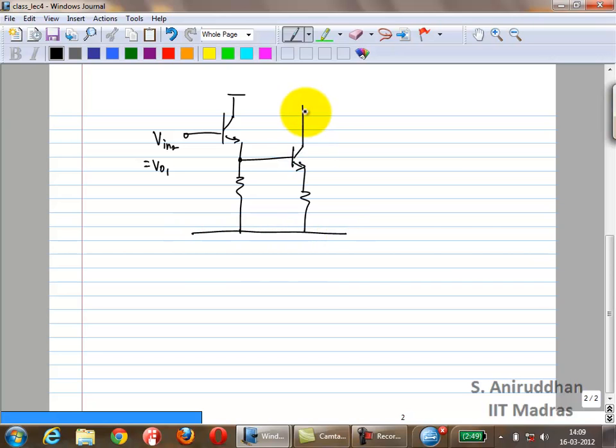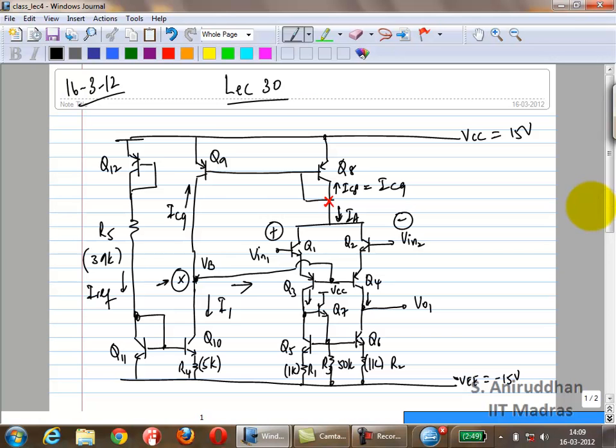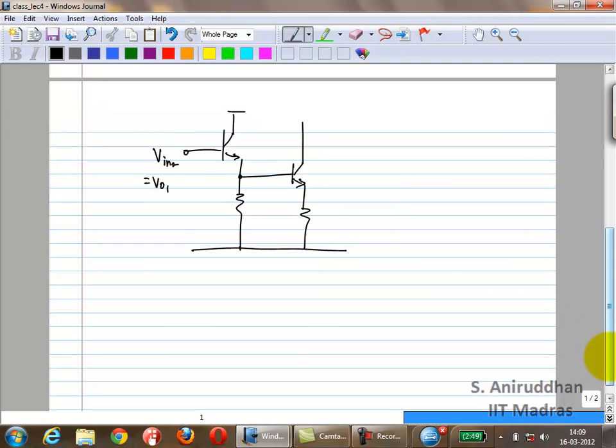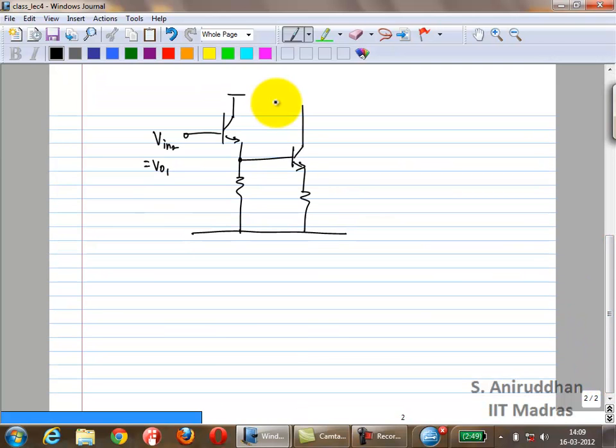The other reason for adding the emitter follower is because you need to take care of DC also, unless you want to use some AC coupling caps or something, right? Because that is actually at 2 VBE, right? We just discussed this. This point is at 1 VBE plus 2 VBE, right? So you need an emitter follower to change the DC. Is that right? Everybody sees that? Okay.